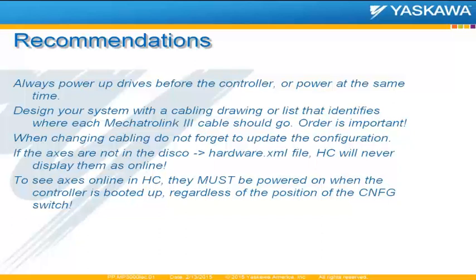Jamie, can you explain a little bit more about the Mechatrolink 3 topology options using the hub? Well, the hub has 9 ports on it. So you can connect the hub to the master, and you can have 8 additional lines going out of there. And the hub reduces your time drastically. You can see in my example, when I had 16 axes in a straight line, I got ranges from 20 to 47 microseconds for my response time.